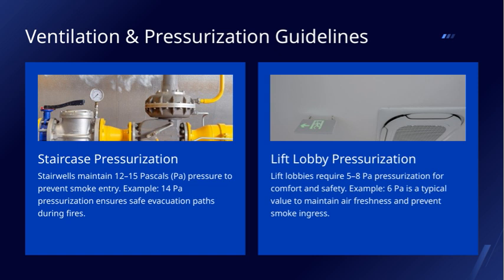Moving on to stairwells, these need to be maintained at a higher pressure, generally around 12 to 15 pascals. For example, 14 Pa is a typical figure used to ensure that smoke doesn't seep into the staircases, thereby keeping evacuation routes clear and safe during a fire.